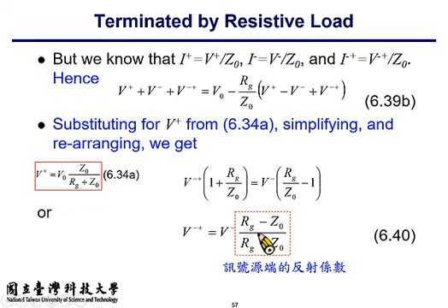So on the right hand side you have Z sub 0. On the left hand side you have RG. So the reflection coefficient seen at this position and in this direction, gamma equals to, which one do we write first? We write the one we look toward first, RG minus the Z0 on our own side, over RG plus Z0, okay?